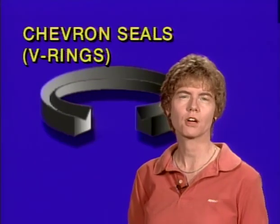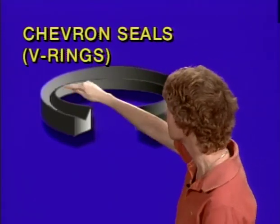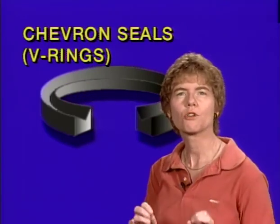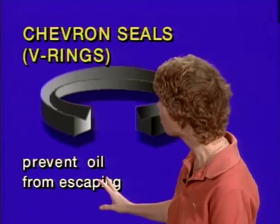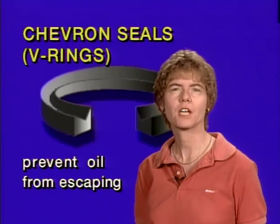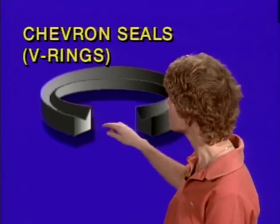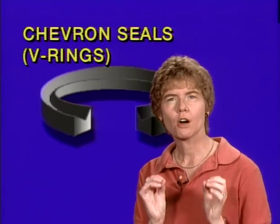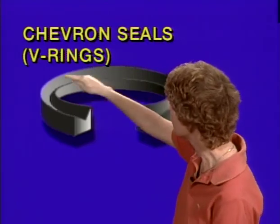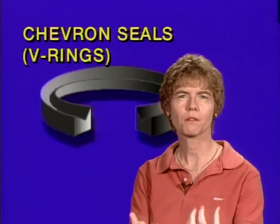Now let's talk about the seals that are used in the shock struts. Chevron seals, or V-rings, and notice the V in the shape of the seal. Chevron seals or V-rings are used in the shock struts, and the purpose of them is to prevent oil from escaping. Not air from escaping, but oil from escaping. And you need to know that when you're installing a Chevron type or V-ring seal in an aircraft hydraulic cylinder, it is the open side of the seal that should face in the direction that the fluid pressure is coming from.